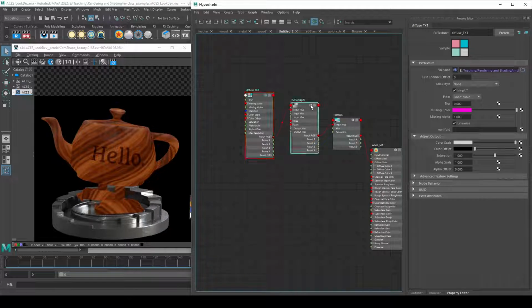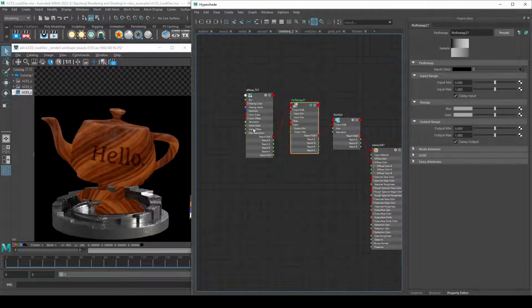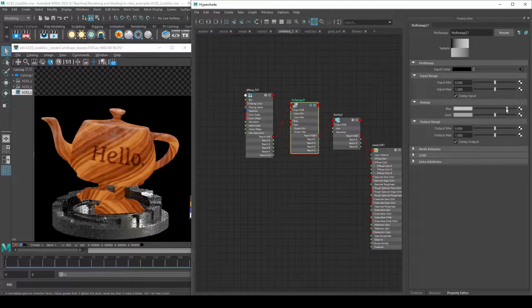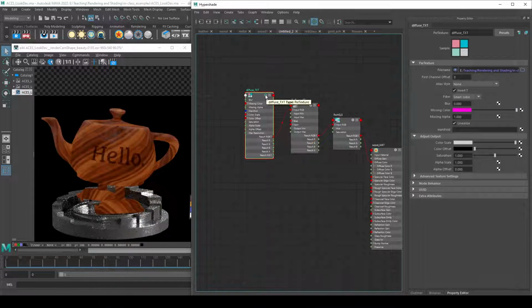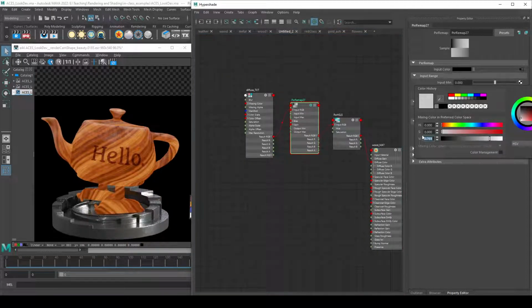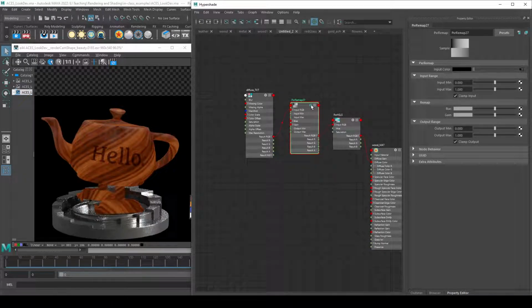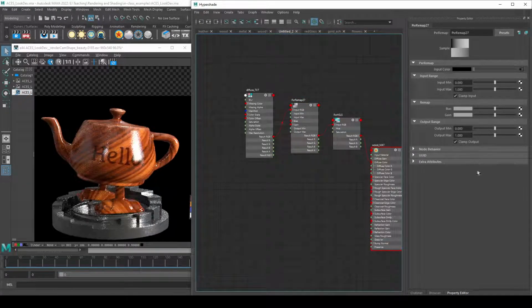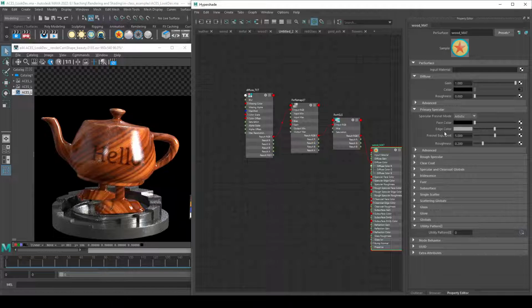And then it can also show me different nodes, right? So that texture map, but being remapped. So if I use that remap node to brighten my texture map, if I look at just a texture map, it's going to show me the unmodified texture map. And if I click on that remap node, it's going to show me that texture map now remapped. And let's go ahead and set that back to 0.5. So just something to keep in mind. All right, so let's go ahead and load in a new, I'm going to reset that.